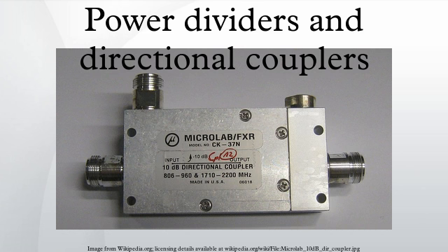High impedance lines have narrow tracks, and this usually limits the design to 3 sections in planar formats due to manufacturing limitations. A similar limitation applies for coupling factors looser than 10 decibels. Low coupling also requires narrow tracks. Coupled lines are a better choice when loose coupling is required, but branch line couplers are good for tight coupling and can be used for 3 decibel hybrids. Branch line couplers usually do not have such a wide bandwidth as coupled lines.